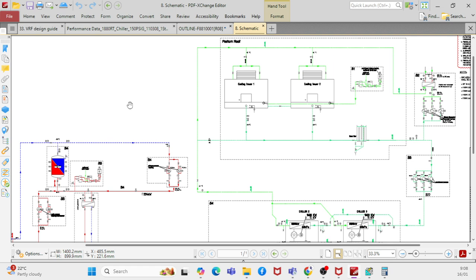No, one point of view is cost. For example, if you go with a 100 liter per second pump for 100 dirham, and another 100 as a standby, then you have to spend another 100 dirham, so you are spending 200 dirham. Whereas with 50 plus 50 plus 50, you will spend only 150. So that is also an important factor. That is why you go with two duty, one standby.